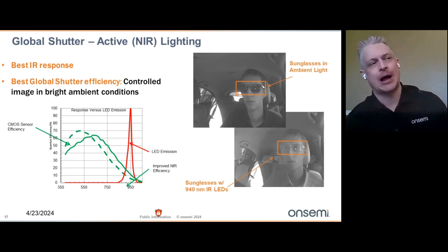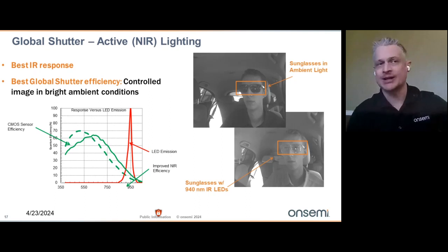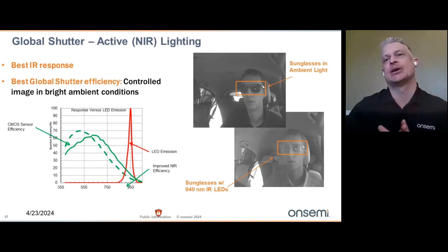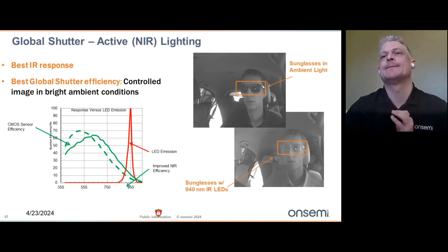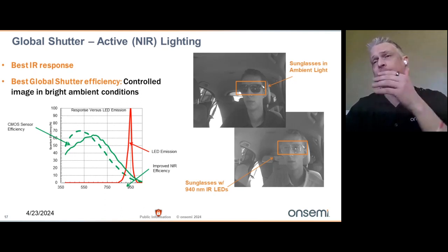And secondly, in terms of power, you generally don't want to expose an LED for 100% duty cycle. So because of this and the fact that you have a very small limited time that LED is on, you need all of the pixels to be exposed simultaneously. So that's the one condition. And then the other condition is sometimes there are just objects that you'd like to penetrate with a deeper wavelength.